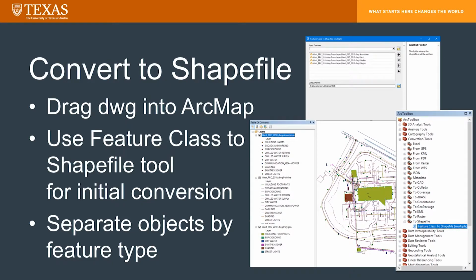During the conversion process, it'll assign pretty much all your blocks to become points. All of your polygons will become polygon files. And this is what Sue spoke about a while ago: if you have a polygon and it's not closed, then ArcGIS is just going to see that as a regular polyline, so it'll put it under the polyline feature class instead of the polygon feature class. So if you actually need things to be closed polygons when you're doing your migration, you'll have to go make sure that all of those are closed polygons.